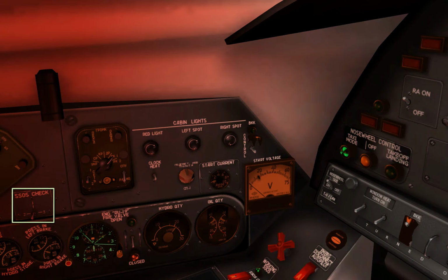This is the GPWS or the Ground Proximity Warning System test switch. The written manual for the aircraft states that when you test the system, the pull-up lights are supposed to illuminate and the buzzer is supposed to sound. However, I tried this switch in all the available 3 positions, but I cannot seem to see anything happening.